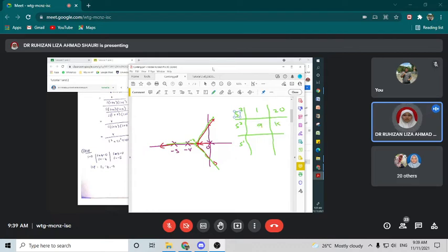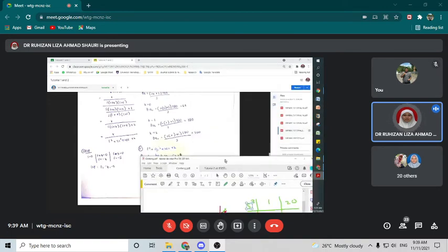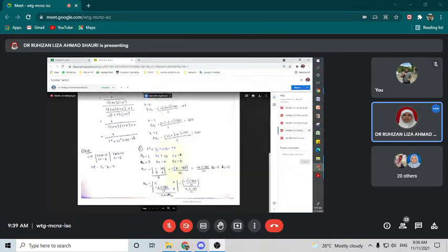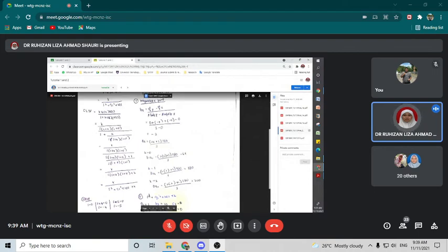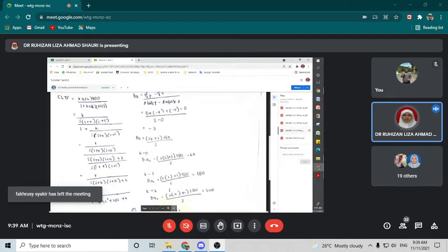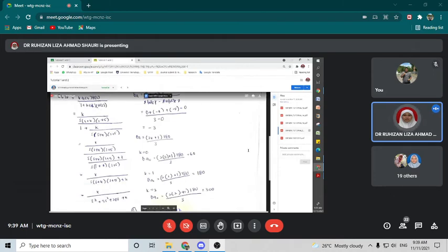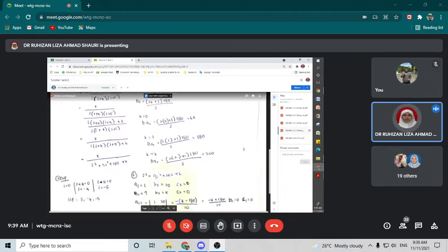Right. Okay, let's have a look at your friend's answer just now for the closed loop transfer function. This is your friend's closed loop transfer function. I'll make it a bit bigger. That should be KG, Nabila. Double check with the equation from the lecture slide: KG over 1 plus KGH. Now that's correct.